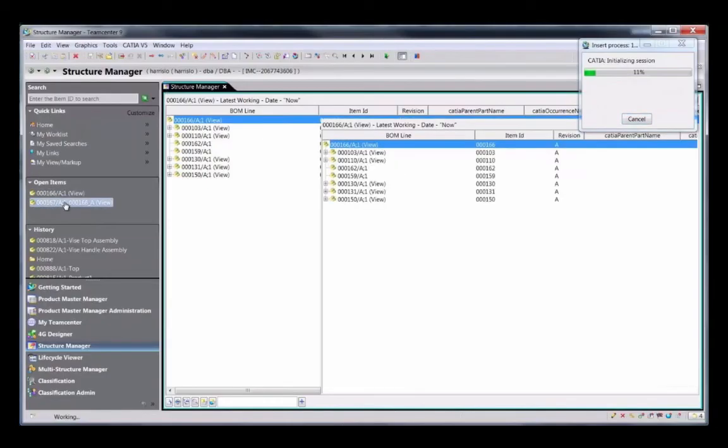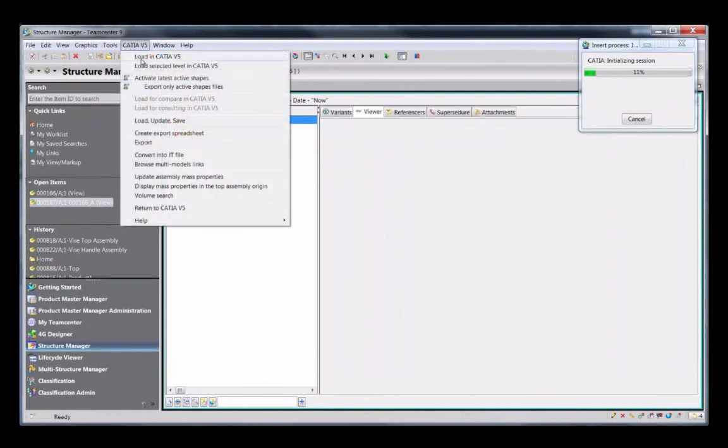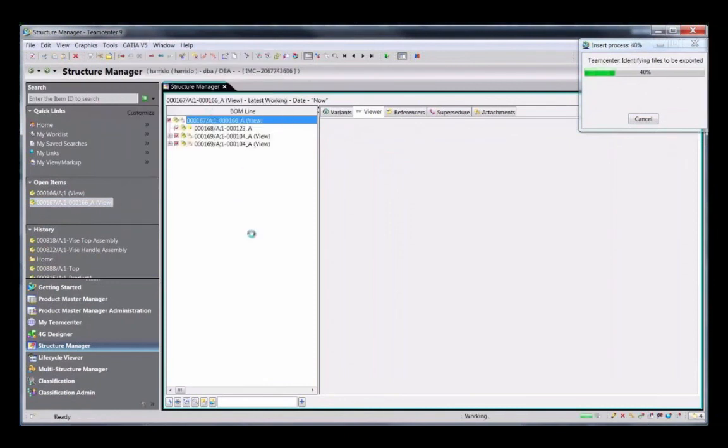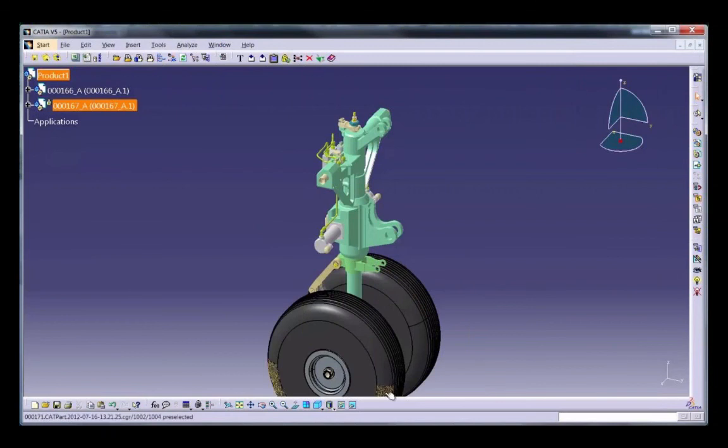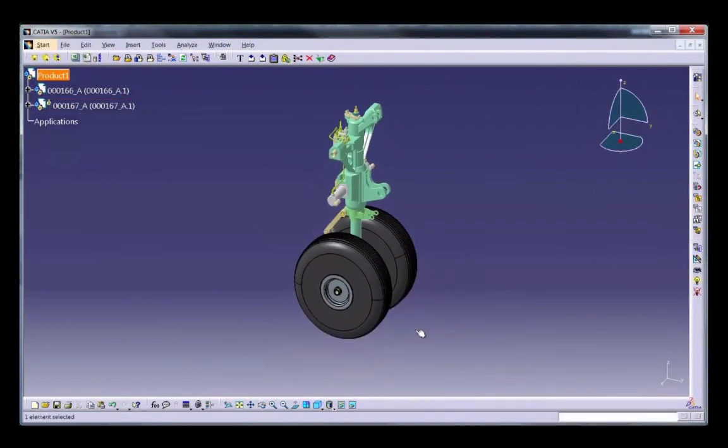Now let me pick the Catia wheel subassembly and load it in Catia too. Right. Obviously, I need to do the positioning if I haven't used a global coordinate system where the workspace is completely defined. In this case, I have to do the alignment work, and the assembly is aligned now.